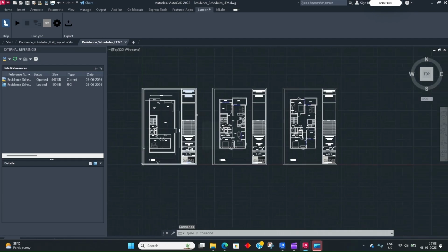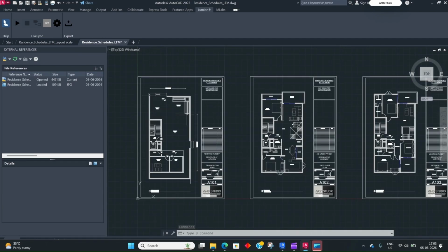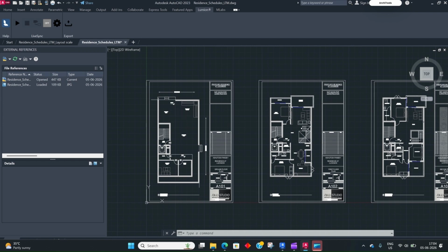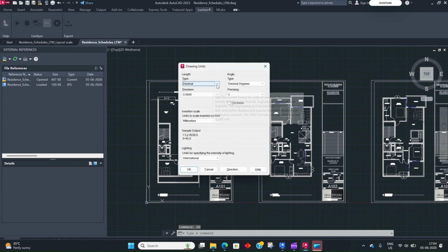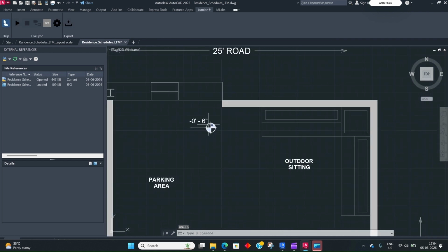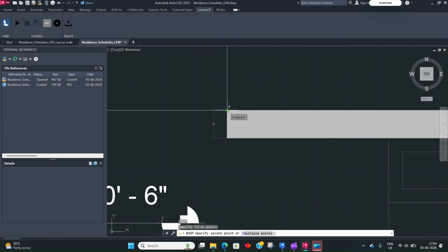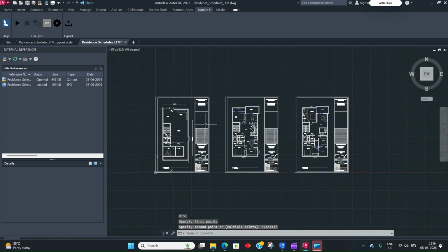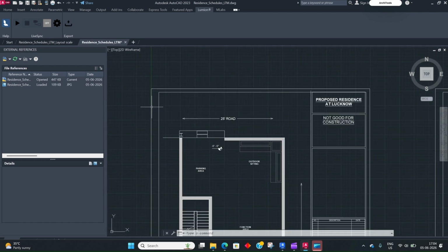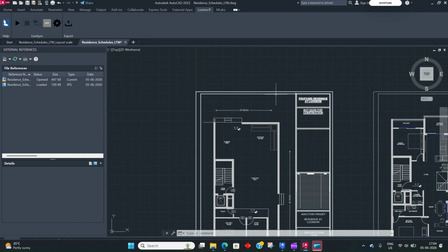Here is the CAD export from the first and the third option. So in this, first of all, I'll just go to units and check the units whether it is matching with my Revit model or not. So you have to first of all check this unit, and after that you can just check the dimension. So my wall was 9 inches thick and it is showing the correct scale for the views. So in order to fit in the views, your scale of the sheets has been increased.